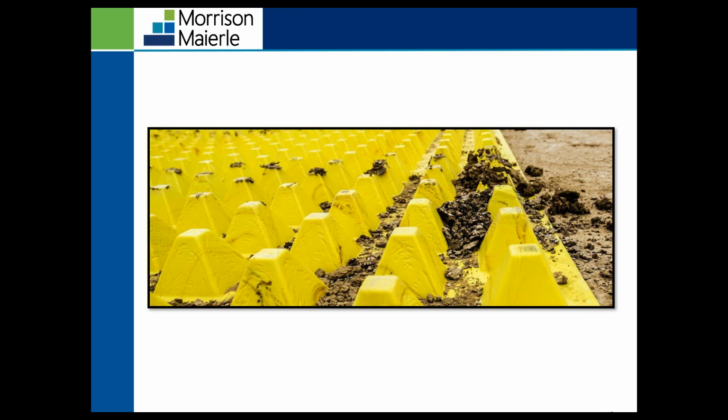Another question is, at the end of the project, do you have to submit your inspection forms to DEQ? No, you keep that. This is for the state. I know some cities do want to see the inspection reports, but as far as this permit with the state, you don't need to submit them, but you do need to have them on file and retain them for at least 3 years. All you're submitting to DEQ is that notice of termination. You retain all the other documents, inspections, and all your revisions to the SWPPP yourself.